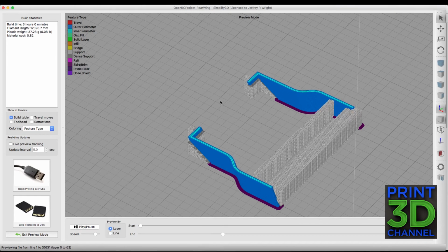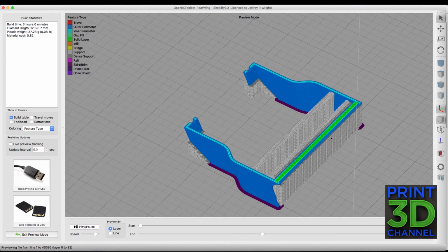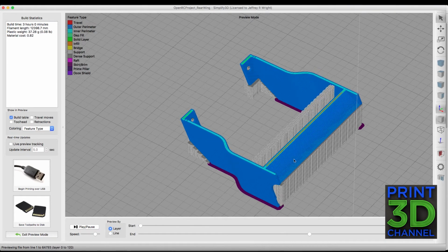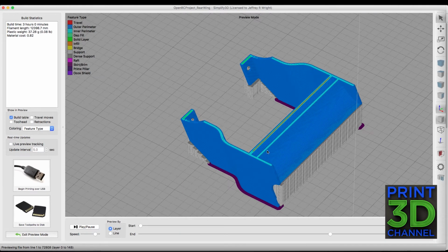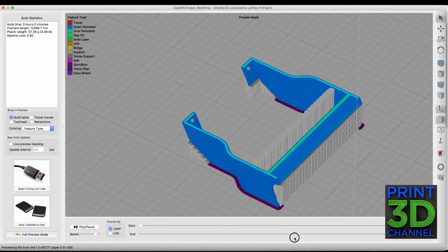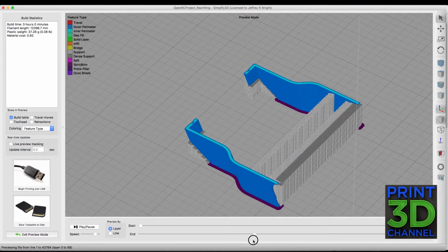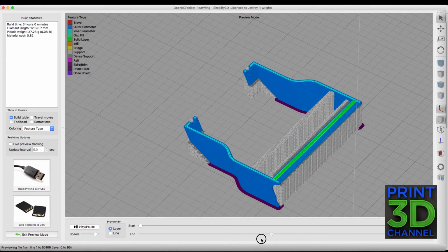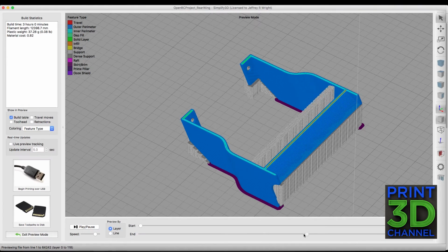It's obvious back here because we have a bit of an air print. But here, I just wanted to make sure the vanes on this rear wing had some support material because those are some pretty long arches to cross. As you can see here, it's going to build a lot of material down there and it needed support there. If I pause this, this will be easier to slide this and show you.